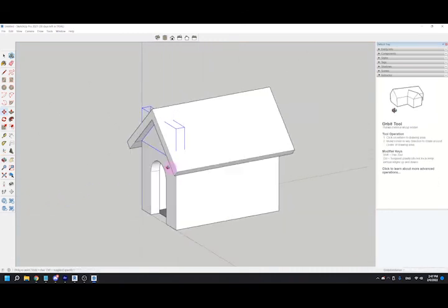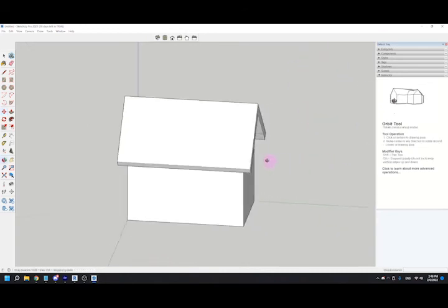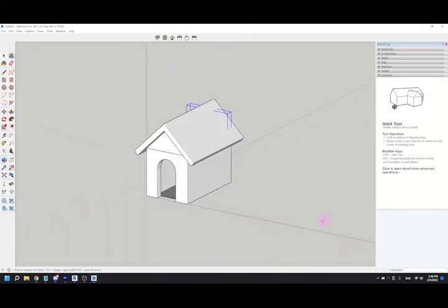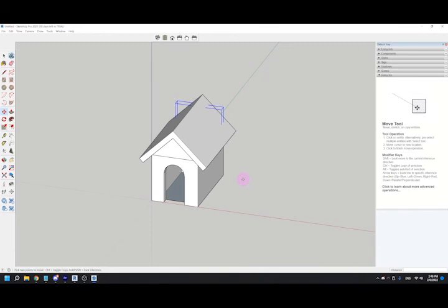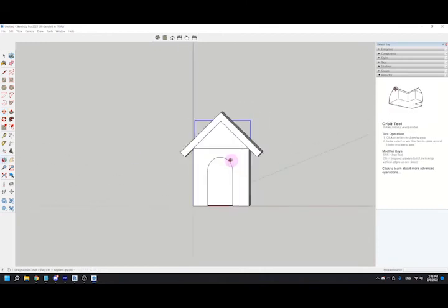And then I'll make a copy of it to put on the other one. So I'll Control C to copy, Control V to paste, and I'm just going to put it floating back here, hold my scroll wheel around to orbit, and then pick it by a corner. I know where I want that corner to go. So I pick it up by this front corner and then place it in that corner. Could there be other ways to do this? Why, sure. But this is how I chose to do it and place it in there. And it works just the same.